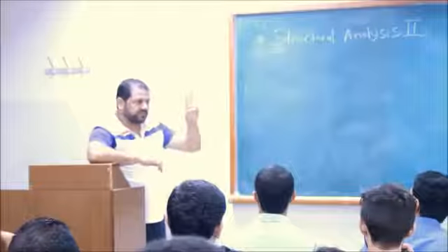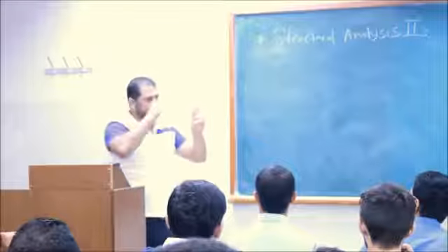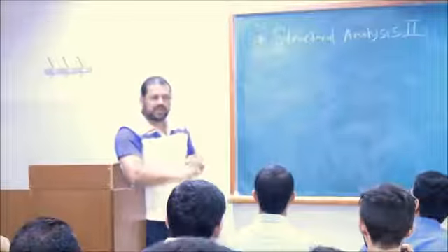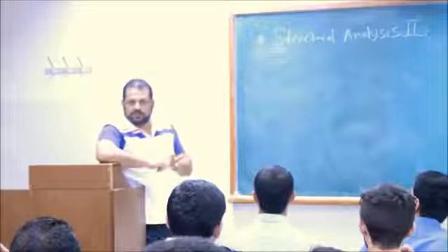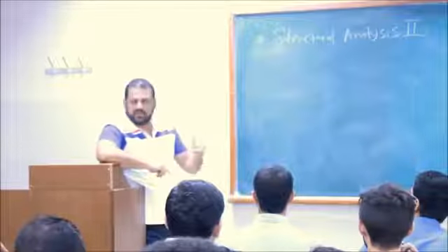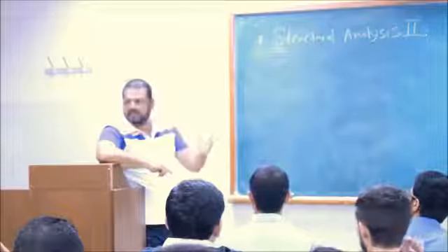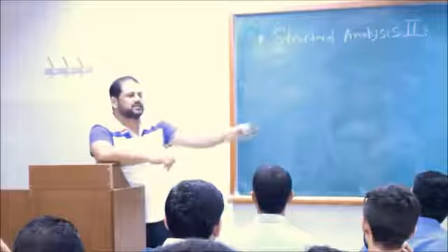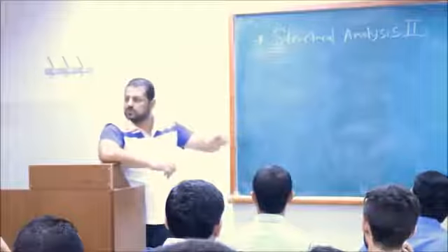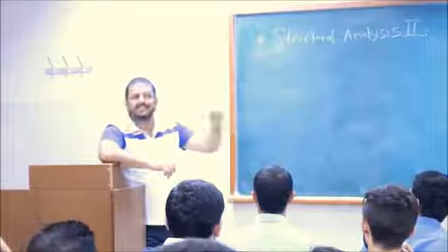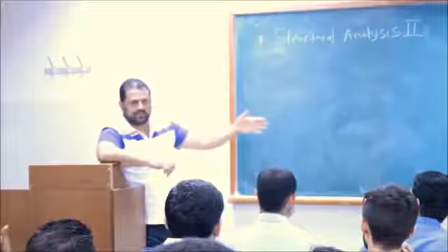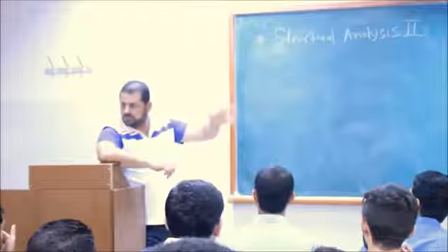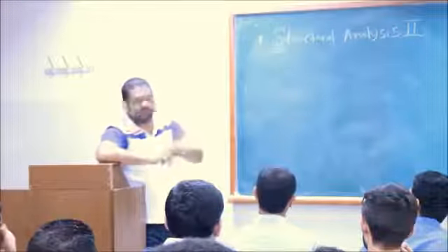So there is two terms you covered in structural analysis 1. Easy terms. Determinacy, whether determinate or indeterminate, and stability. Okay, so we check determinacy and we check stability. If the structure is unstable, you don't have to check it. Unstable, it's kind of you forget to tighten something. Something is loose. Something is not restrained in one direction, whether vertical or horizontal or rotation. If you load it, it will rotate.